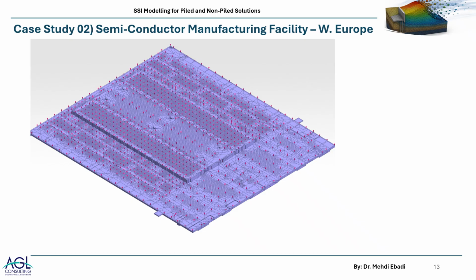So you can have different load cases. In each load case, you can apply loads to different nodes, and then by having a combination of those load cases, you'll have different combos for different conditions.